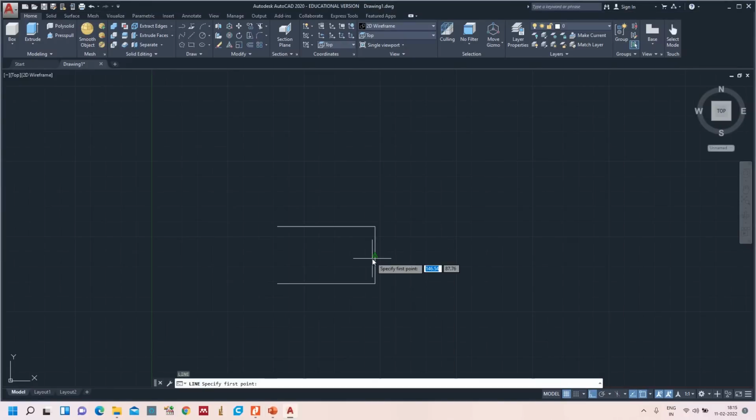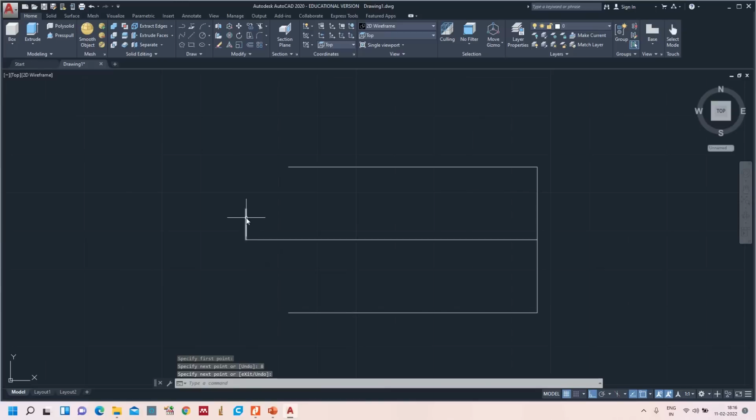So take the length as 75 mm, and now here 8 mm. So here this is an individual line of 8 mm. So next, don't draw a line of length 8 mm again. Just click it and place the cursor here. It will ask you to stretch or lengthen. So I am going to stretch 8 mm. Yes, now this is a single entity. Now connect these lines.